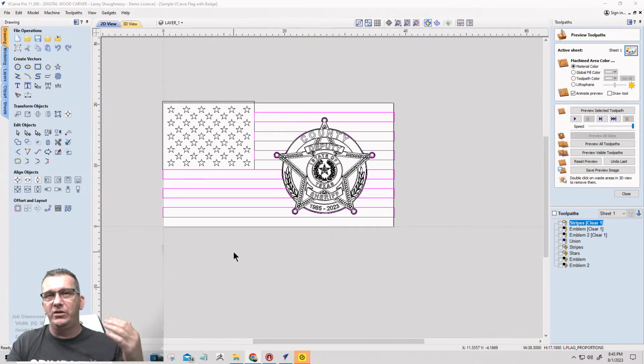So when you hear the term speeds and feeds, the speed side of that is the rotation of the bit, the RPMs. Now, no one with a mid-size unit should be running any bit over 18,000 RPMs. There's no need for it. There's no need to be at 20, 22, 24,000 or anything.